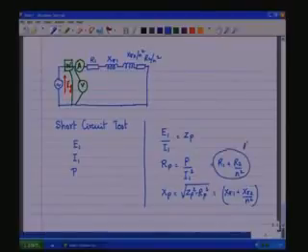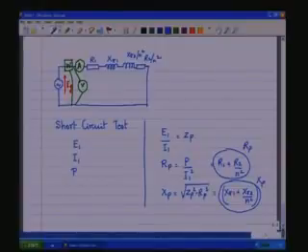So, this is RP, and so RP gives you the total reflected winding resistances of both the primary and the secondary as seen from the primary side. XP gives the total leakage reactances of both the primary and the secondary side reflected onto the primary side as seen on the primary side. So, this gives you the leakage reactance, and this gives you the equivalent winding resistance.